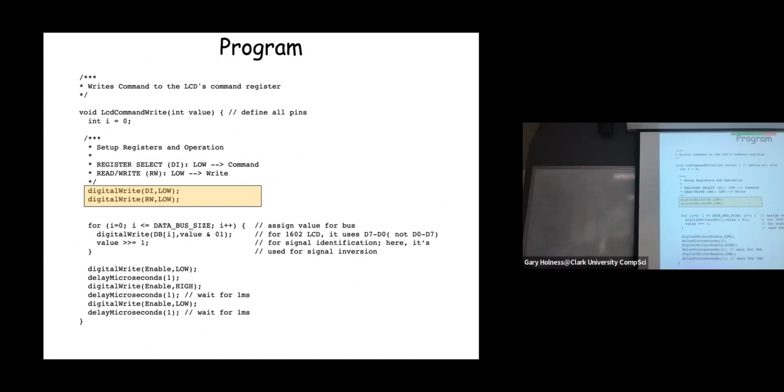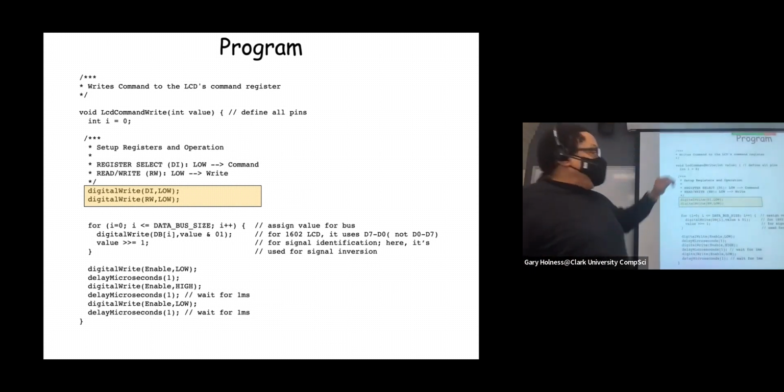Yes. Well, when you say write something, write doesn't mean the data. Write means the command. And so, for example, one command is clear the screen, right? You clear the screen, and then you present the data, and then you say, write that data to this part of the screen, to that address. And so you have to do the writes and the reads interchangeably at different times. And the problem with doing it in the setup is that setup only happens once, but you want to do this multiple times, because at one point, and when we get to giving it the data, you'll see the difference, at one point you want to send it a command. At another point, you want to send it the data.